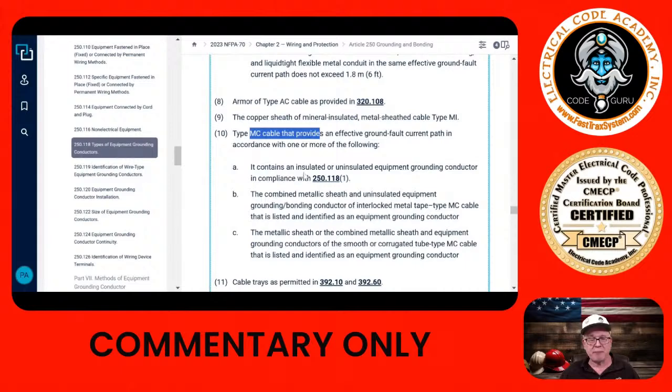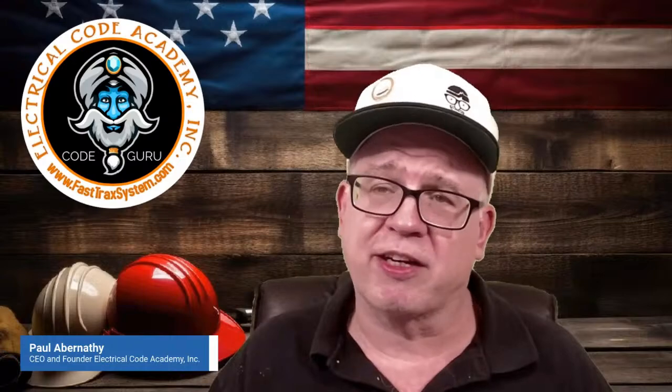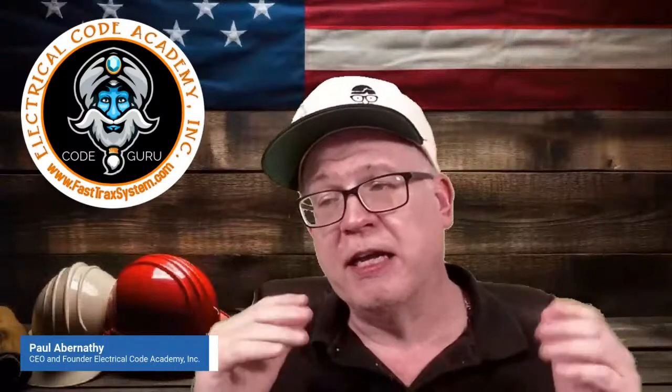MC cable, typically standard MC cable, again, comes with an equipment ground inside of it. And that would be okay if that was included, but in our picture, it wasn't there. Then people say, but don't they make an MC cable where the armor can actually be used as an equipment ground? And they do, just not with conductors inside of it larger than 6 gauge. Okay, so 6 gauge is that limitation on that type of product.